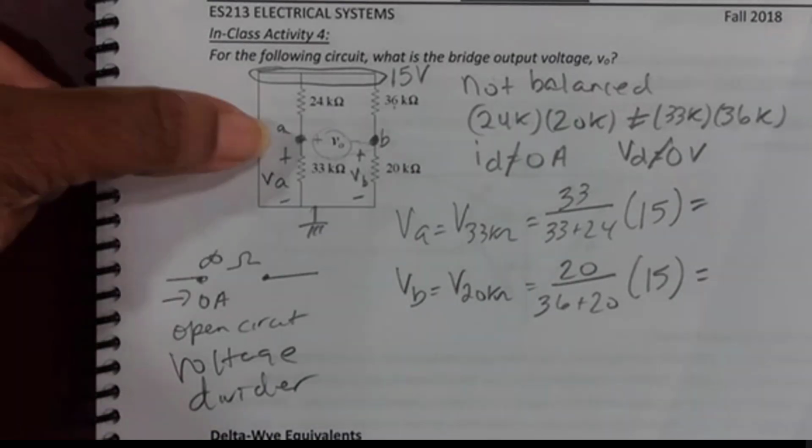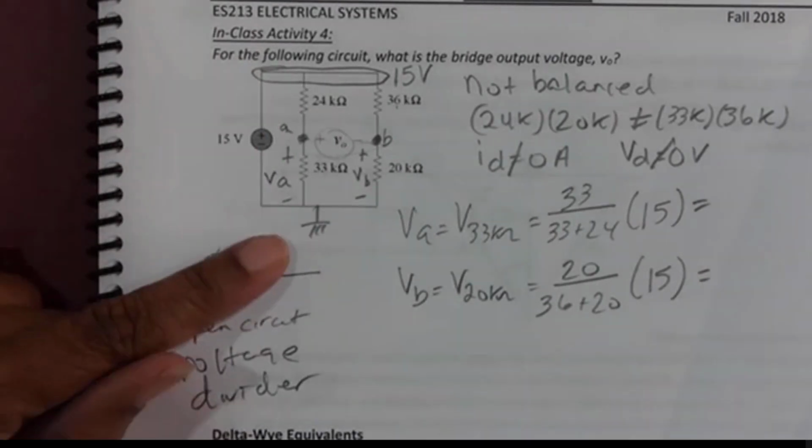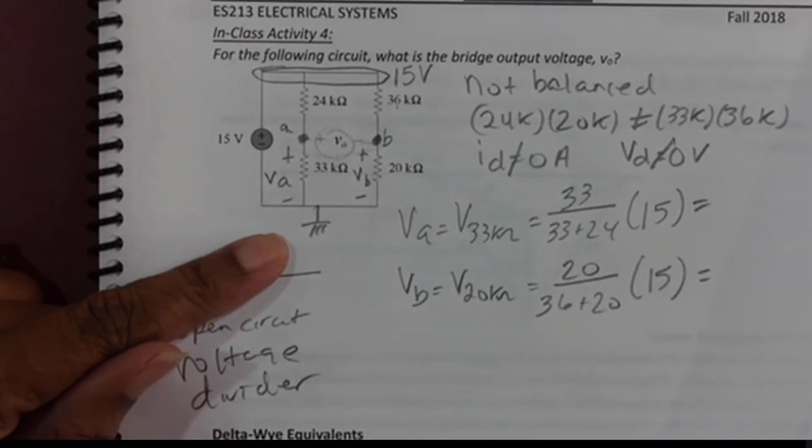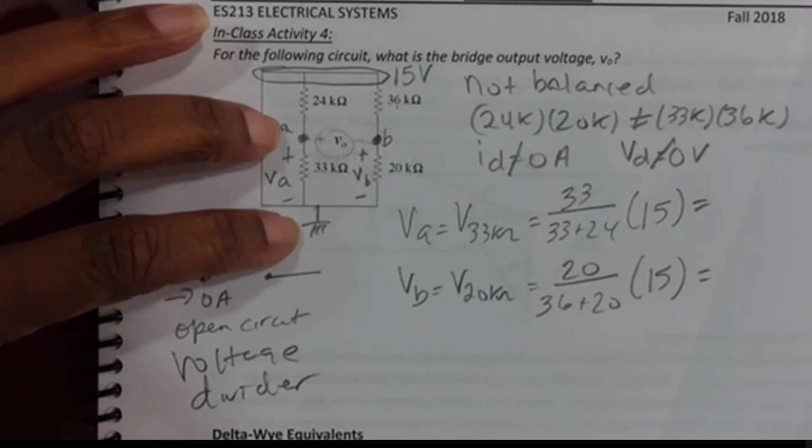Okay. So when you're looking for a node voltage, you guys also did this in lab yesterday. You always put the black to ground. And then you touch one of the nodes, and that's the node voltage with respect to ground.